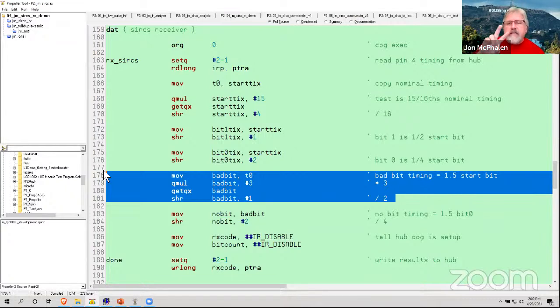There are two settings. There's an indoor-outdoor setting that is completely current-based. So we have two FETs that will switch things in the IR circuit. One of them does the modulation, so we can modulate it and send the output. The second one will either allow another resistor in line or bypass it.